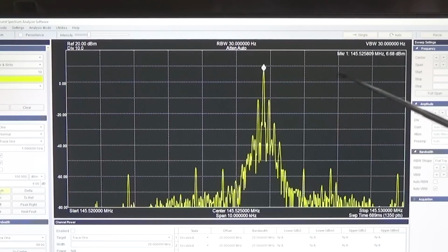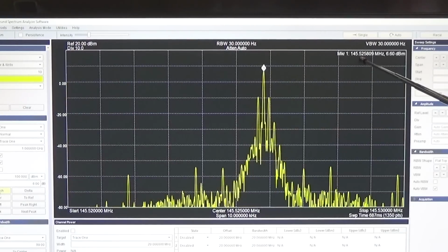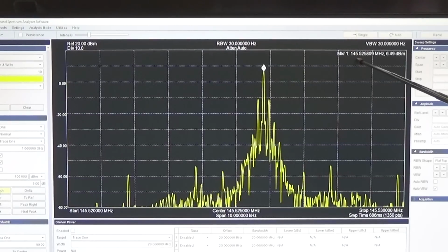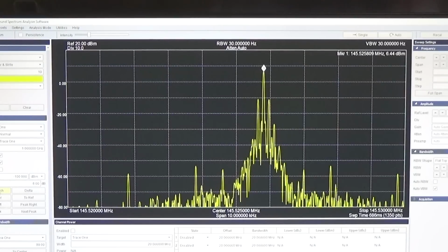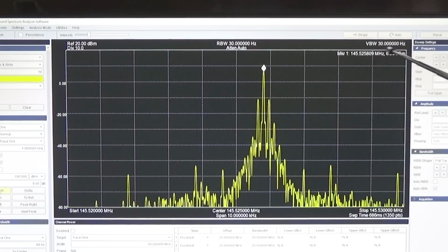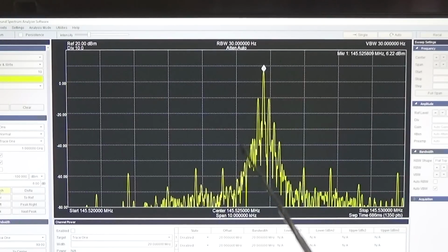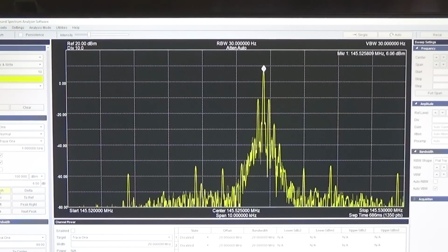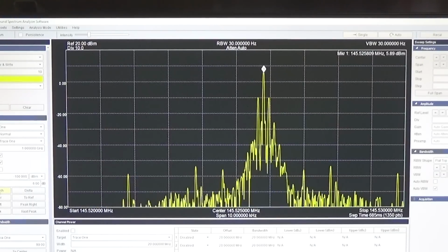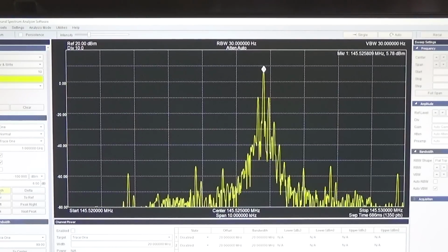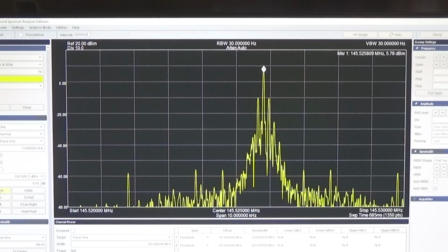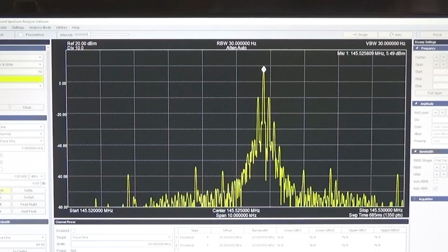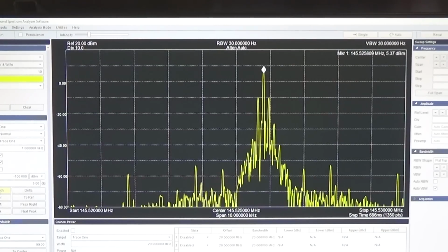But more or less the carrier is there and it is more or less on the right frequency, so 145.525 megahertz, but of course we are too high, so the carrier should be here in the middle, but that is a second issue, because the carrier is out of frequency, which means that most likely the reference oscillator is not aligned after long years of operations.